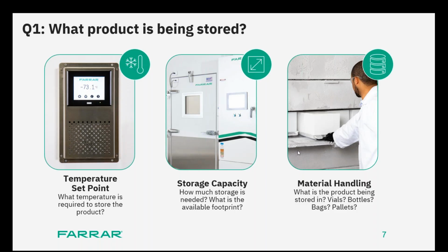And then we're also going to look at the final aspects of what type of equipment you could have inside of your chamber that generates heat. For example, if you have many convenience receptacles inside, are you plugging shakers into them or other equipment? Or are you going to come in with a fork truck going in and out, generating heat? We want to know all those items because it helps us properly size, and down the road we're also going to be able to mitigate and manage all of your defrost needs inside of a chamber.